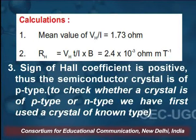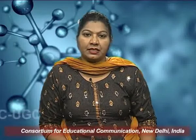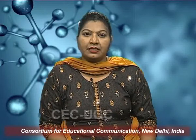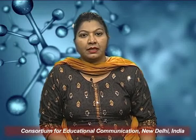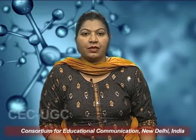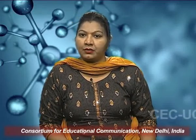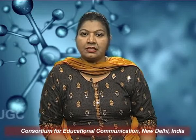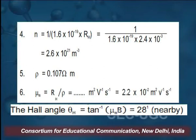If the sign of the Hall coefficient is positive, the semiconductor crystal is of the P type. If it is negative, then it is an N type semiconductor. To check whether the crystal is P type or N type, we first have to use a crystal of known type. Then after that the unknown crystal we can put in, and we can find out the Hall coefficient or the charge carriers. If it is positive, then holes, negative for the N type.